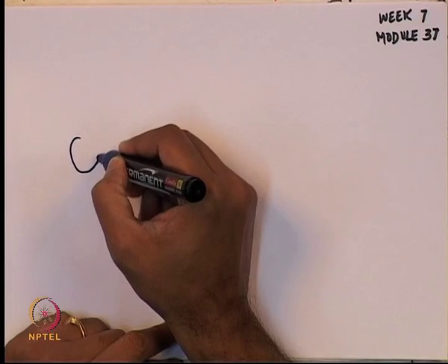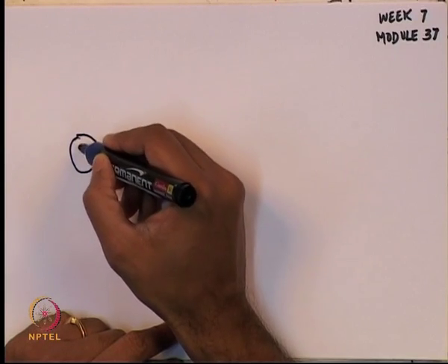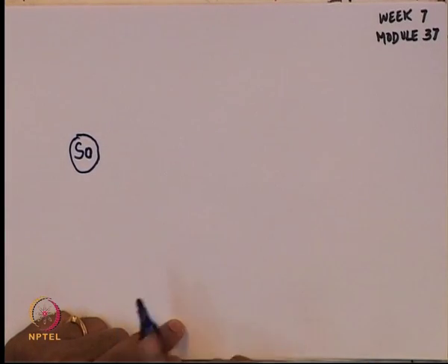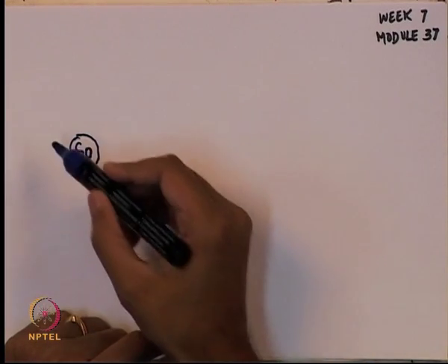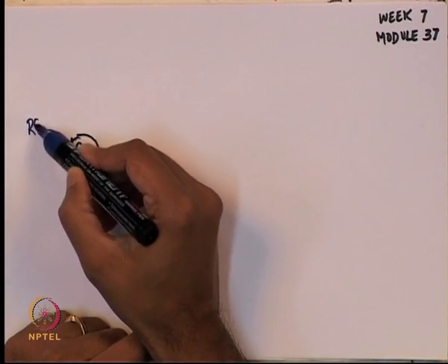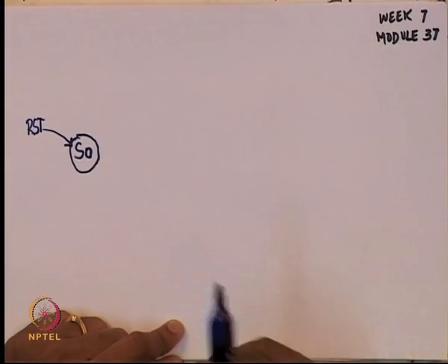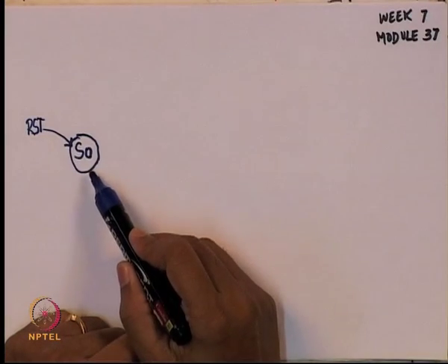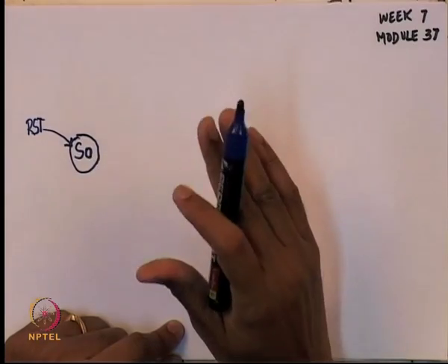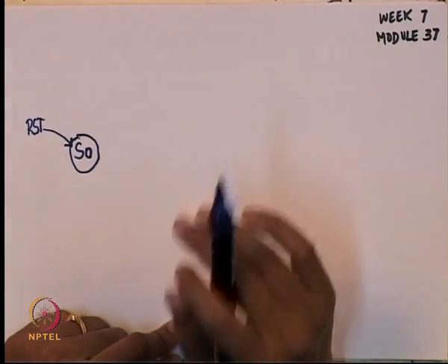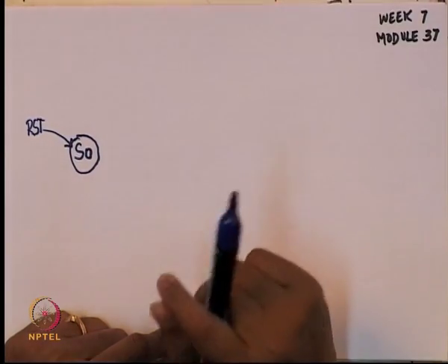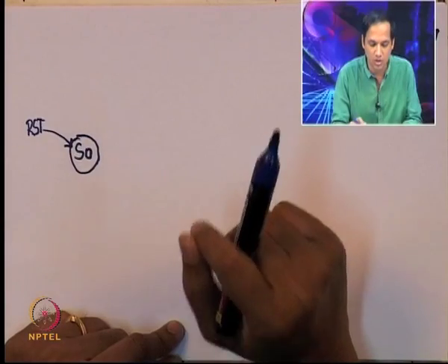I am going to start with something called the initial state. So, I am going to call the state S0. The S0 is supposed to be an initial state, and when I reset the machine or when I do a start, the state machine is supposed to come to the reset state. Remember the protocol that we had is the external world will place the 2 inputs at input in1 and in2, and then will turn on a signal called go.